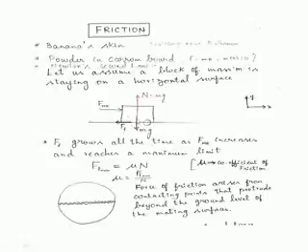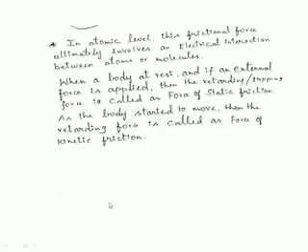Why does friction actually develop? If we zoom this contact surface 1000 times, we can see that there are some surface irregularities, some protrusions. Because of these protrusions and irregularities, upon applying a force, there will be some resistance offered by these protruding surfaces, which will resist the motion. At the atomic level, there is also a lot of electrical interaction between the atoms and molecules, which is also a part of the friction.